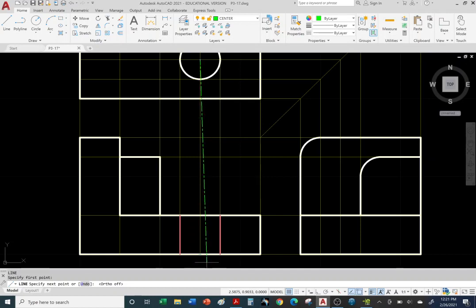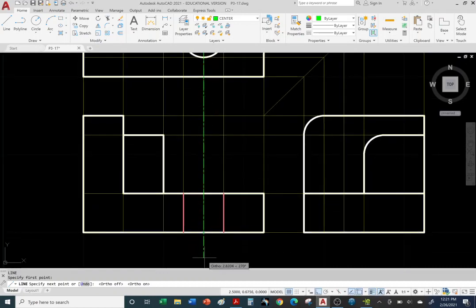You don't want to go off a little bit at a slight angle from the vertical. And I'll be able to tell, right, when I open your file, if it's slightly off, I will take points if your line looks something like what we're currently seeing. Okay, let me turn on ortho to guarantee a vertical or horizontal line and go beyond the object line. How much? Just guesstimate. If you just go a little bit, it doesn't look as clean. It's better to actually overextend than to just slightly extend. Okay, so you can always readjust it and click.